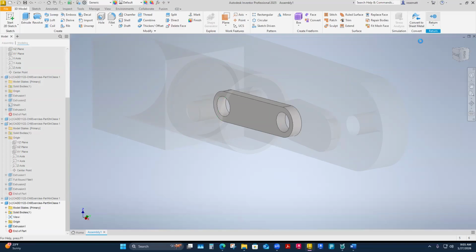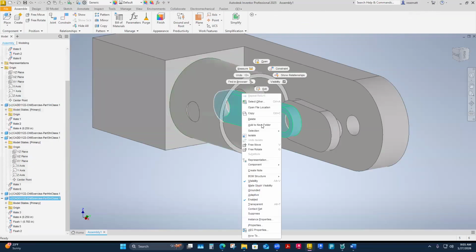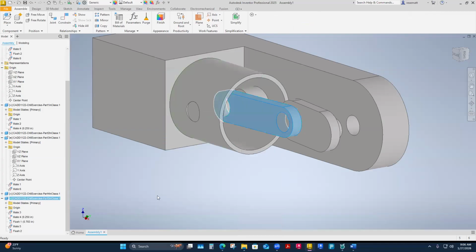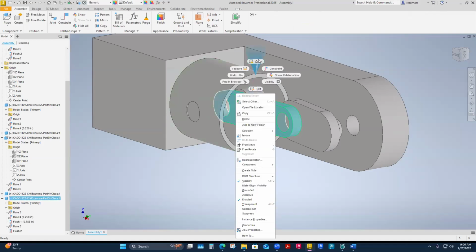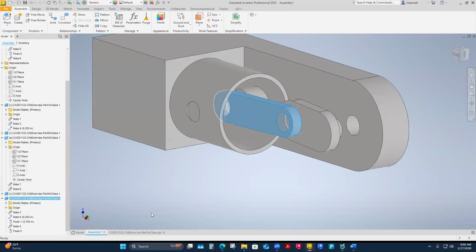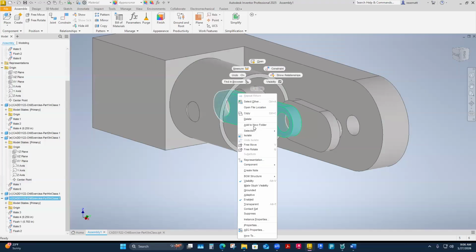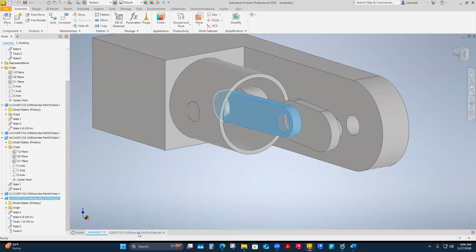Is your edit grayed out? Yeah. It won't allow you to change that, huh? This is not allowed. Yeah, maybe close. It wants you to close the part before you edit. That could be true. Oh yeah. So if you have this open, that makes sense to me. I can kind of remember that. I have my part open now. Edit's not available because I have the part open. So yeah, close your part.